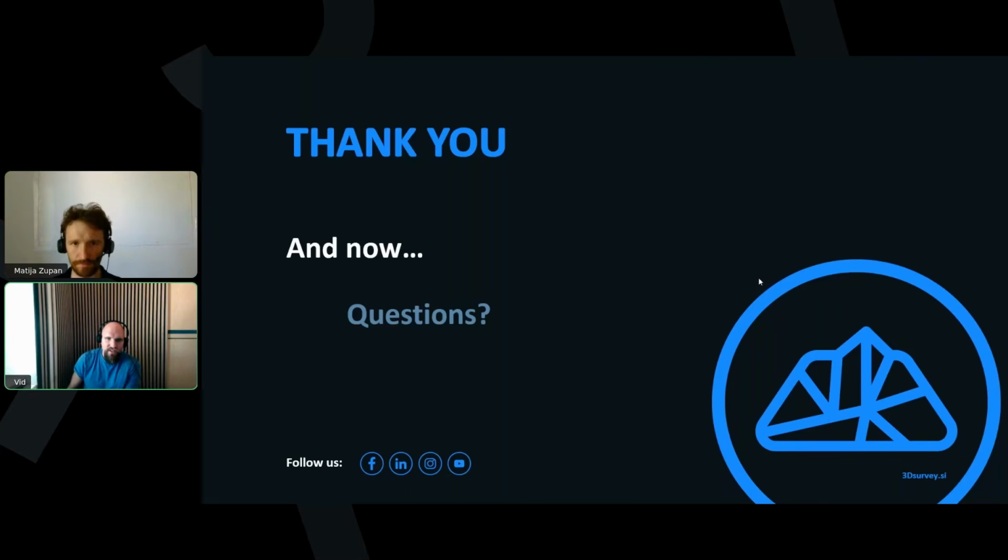Then for the second part, which is SLAM processing, for the raw processing of SLAM scans, you put it into the software that comes along with the SLAM scanner. Again, part of the calculation is run on the GPU, and again you run it on your local desktop computer. This time, I think we had a bit over 30 minutes of scanning time. The processing of raw data took, I would say, between 8 and 12 hours, something like that. So the SLAM processing is still done in a separate, native software that comes with the hardware, and after that it's imported in 3D Survey. So it does need some processing.